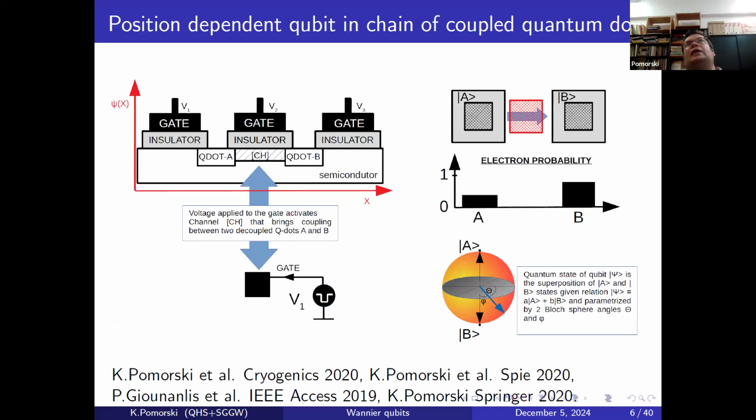This is a way of thinking that is associated with a situation where you want to use the current state of the art of CMOS technology, which is highly developed. But you can also forget about CMOS technology and just manufacture your own quantum dots and have a similar scheme. So when we talk about CMOS technology, then you have a transistor that has gates, voltage-controlled gates, and then drain and source can play the role of the left and right quantum dot. That's a left and right localized area. That's how it is.